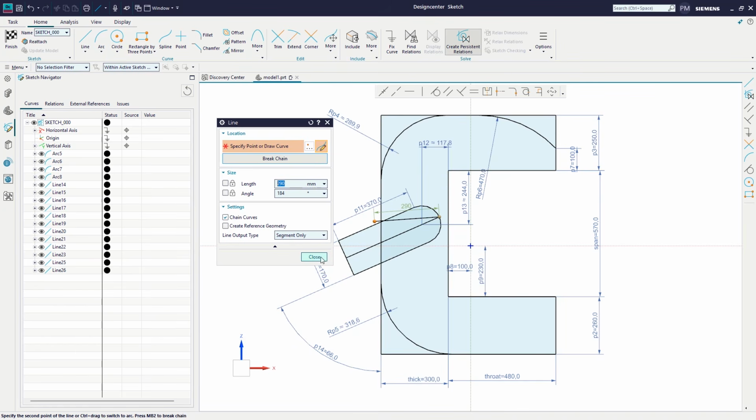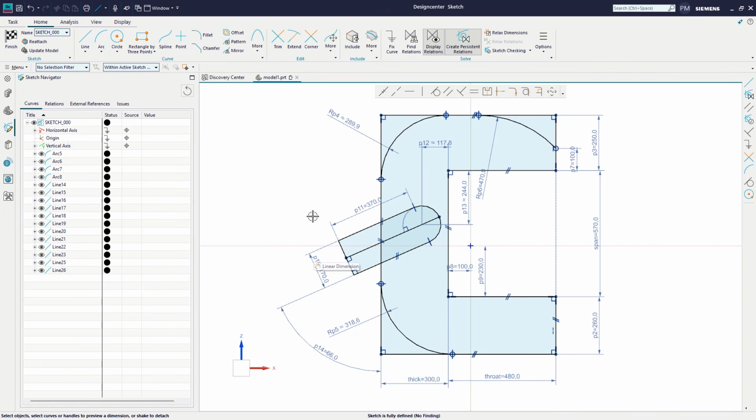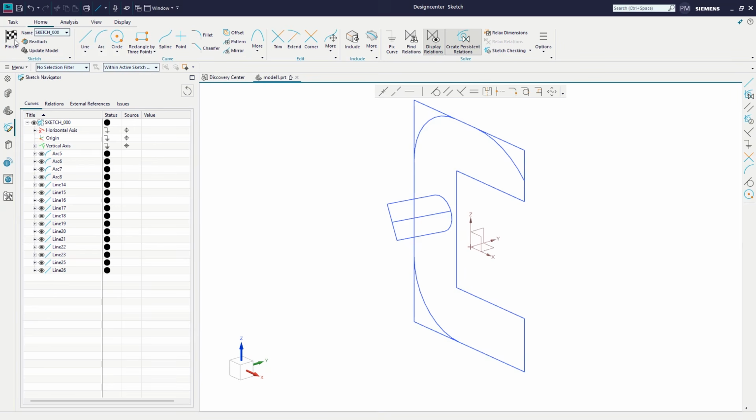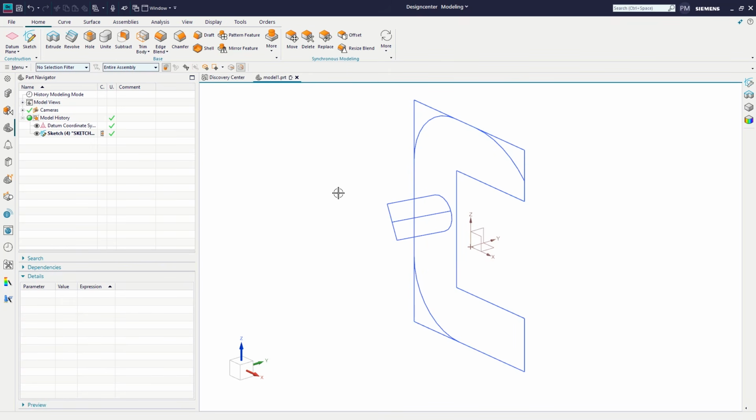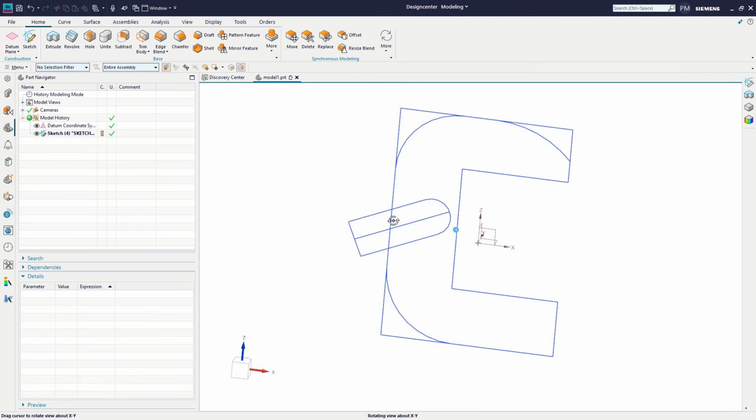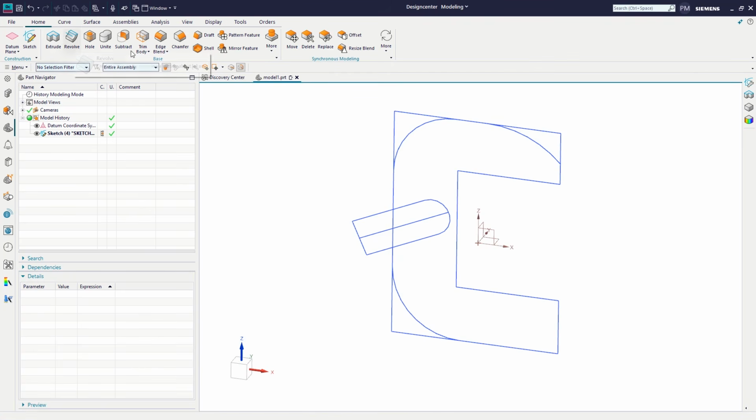You notice that I chose not to trim all the sketch curves back. That's certainly an option and is the way some users prefer to work, but I prefer to keep my theoretical corners and other construction geometry untrimmed if I can, in case I want to reference it later. But I can still virtually trim it as part of the actual extrude command or any command that uses the sketch. And this is also what allows me to include both features in the same sketch without them conflicting.